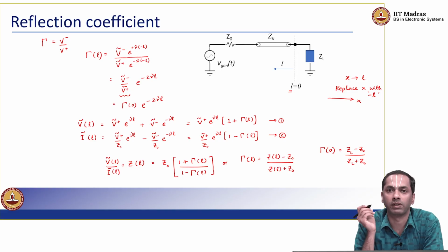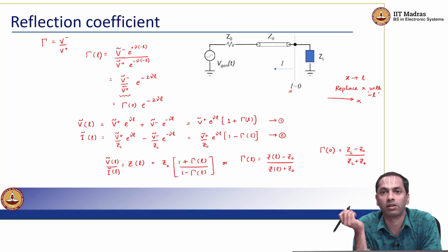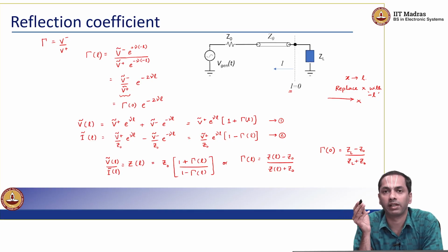So that is a very key insight. Even though there is a fixed complex impedance connected to the end of the transmission line, depending on where I look along the transmission line and measure the voltage and currents locally, I don't get the same voltage-current relationships that I should observe when I apply the voltage directly to the complex impedance, right? So I actually get a different relationship between voltage and current along the transmission line, which is now spatially varying, right?